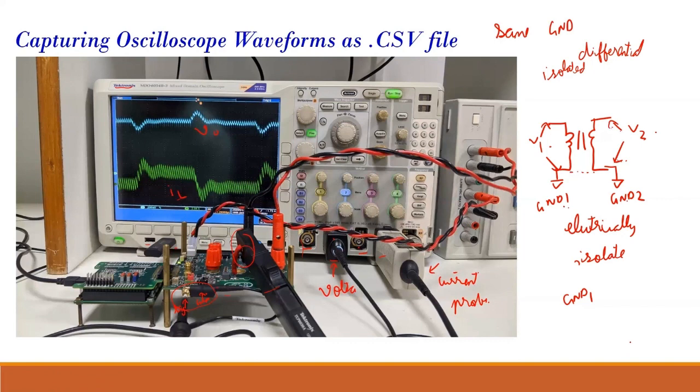Yes, sir, suppose we are using transformers in the circuit that you have drawn. If I want to measure the voltage in the primary and secondary, then I need to use two different DSOs. Yeah, you could do that, or you could use differential probes.